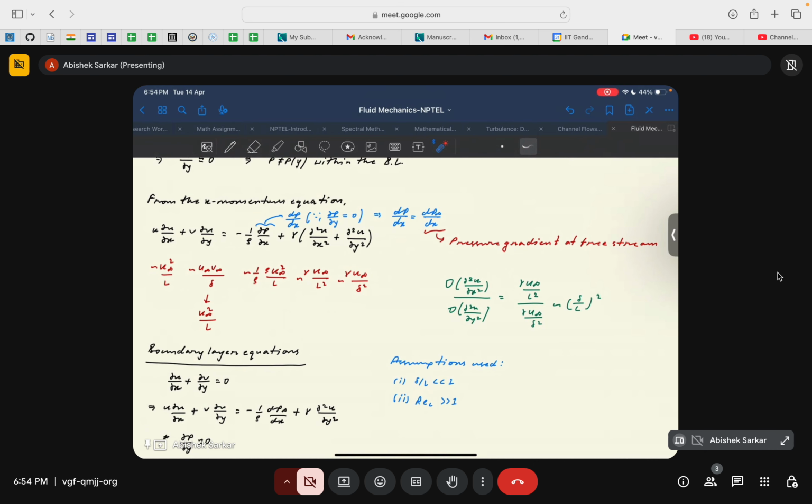That's why the velocity gradient along the y direction intuitively becomes much larger than the velocity gradient along the x direction. So this term essentially cancels out, and we cannot cancel out these other terms, because if we cancel them out, then there is no term that tells us the source of the flow. Okay, so these terms imply inertia, which are indeed the source of the flow. These are terms that generate the flow. So if we cancel out these terms altogether, then there is no flow, right? Then there is no point of solving the equations. That's why in that sense also we cannot cancel out this equation.